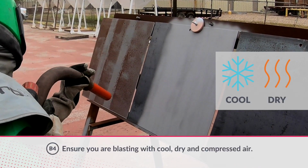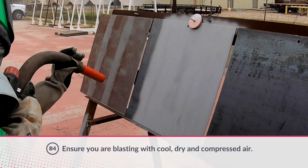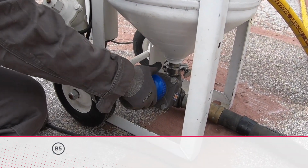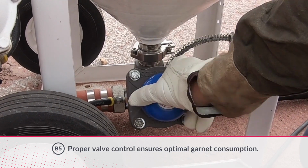Increased moisture can increase garnet consumption. Dry air ensures proper flow of abrasive through the blast pot and metering valve. And having proper valve control will ensure optimal garnet consumption. The blaster first needs to completely close the metering valve. Open the valve with a few turns.